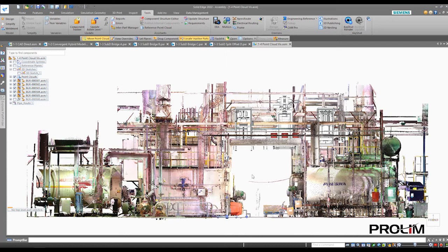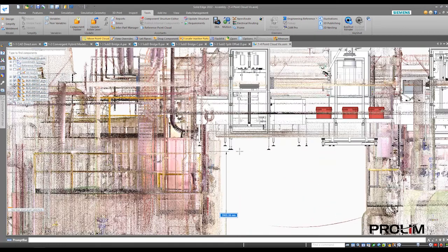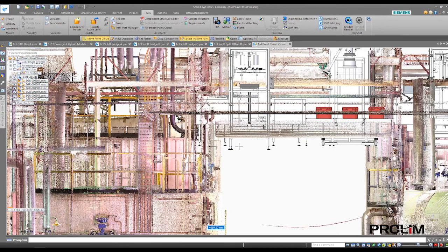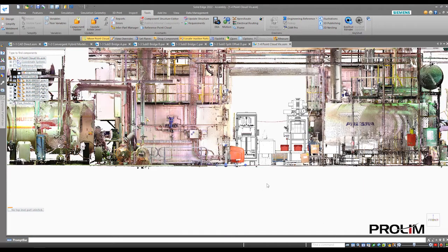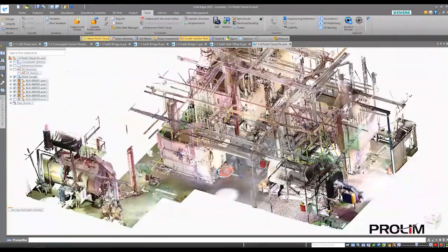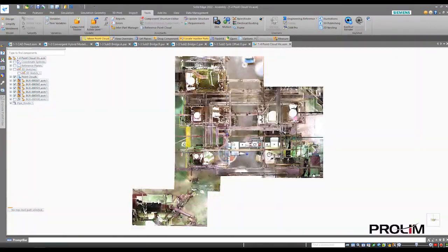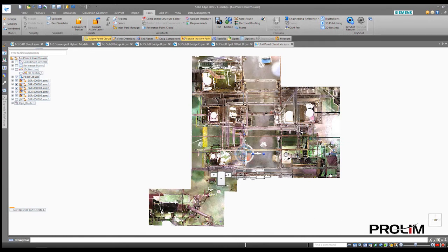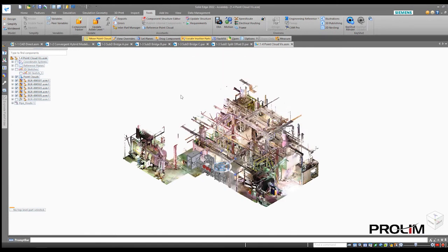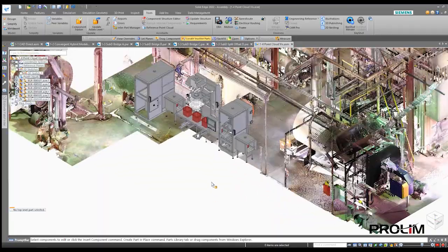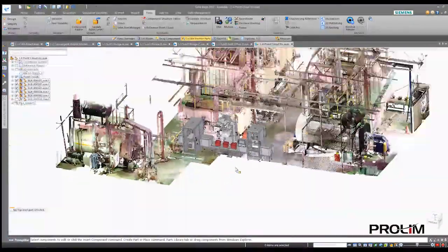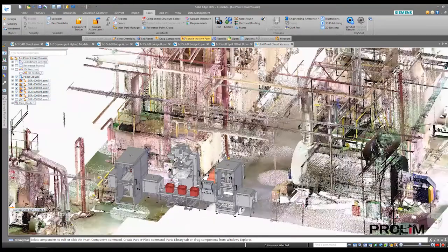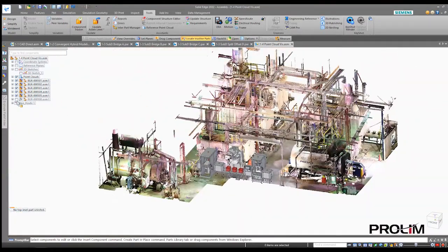It's just much easier to move this one piece of data as opposed to trying to manipulate my entire assembly. Using those synchronous style steering wheels, you can see that I can pretty easily manipulate this to where I want it to be. Let's go ahead and pull this out about 3,500. There we go. Okay, so now we've got this 3D point cloud data pretty close to what we want to see here. I'm going to go ahead and activate a couple more parts here.